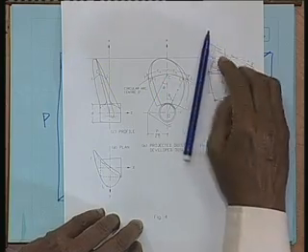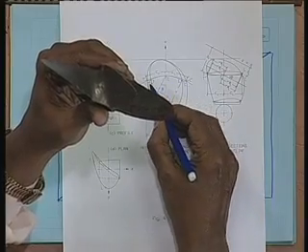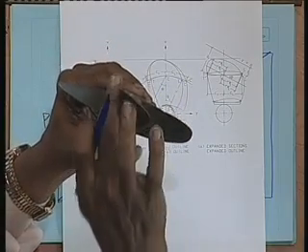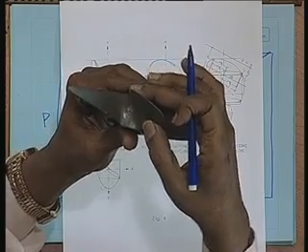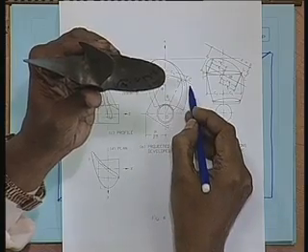Now, there is an outline called the developed outline. You see what we are getting: the projected outline is, if I had R here and I drew it, if I took the photograph here, how that line would look, that is this circle T, C and L, isn't it? That is how I am drawing the projected outline. Now, suppose I do not actually make it into a straight line, but bring this circle to a single plane. This circle is in 3 dimensions. If I bring this out to 2 dimensions, then I will again get a line which is more than the projected line.